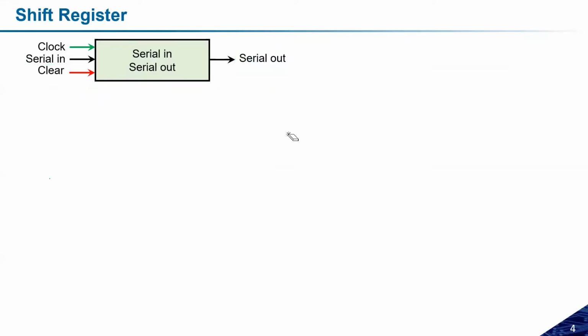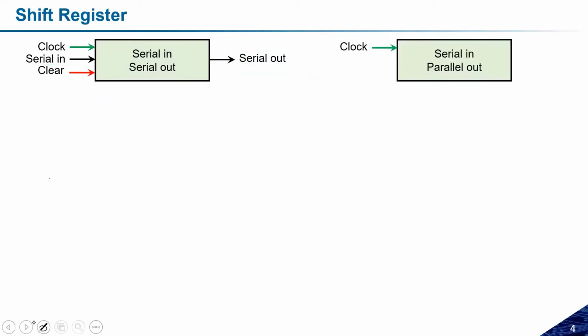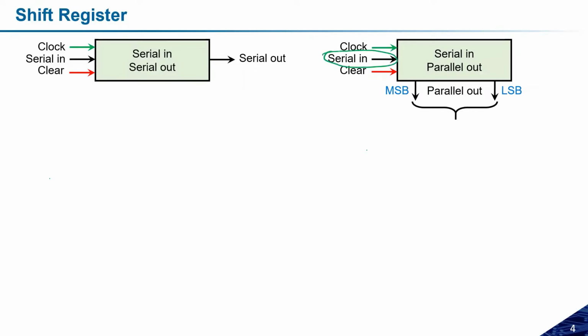So this is the delay and the importance of this serial input, serial output kind of register. Now let us talk about the second category, which is the serial input, parallel output register. All other things are the same, only the output will be taken out parallelly. So the input will be given serially and the output will be parallel. Initially, let us assume it is a 4-bit register, 0 0 0 0, and the output will be 0 0 0 0. Now let us assume I am giving the input pattern 0 1 0 1.